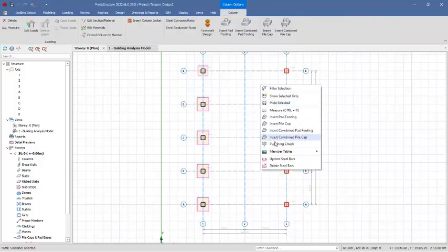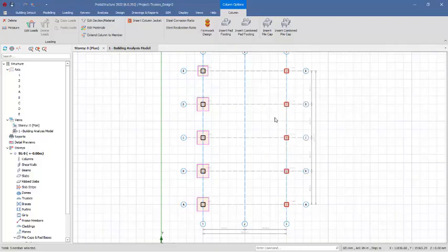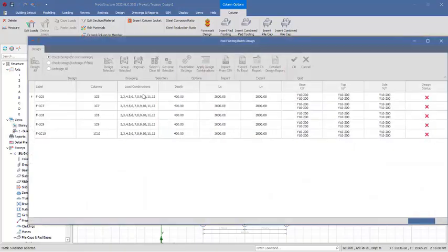So once the design is done, it will show us a green check just like this. You can see now, green check. Alright, so we're having Ls, Ly to be 1.4 by 1.6. So this is one of the disadvantages of designing by grouping, because it's going to give you larger sections of the footings. Because it's going to pick the highest footing size and use it for all of the rest of the footings successfully.